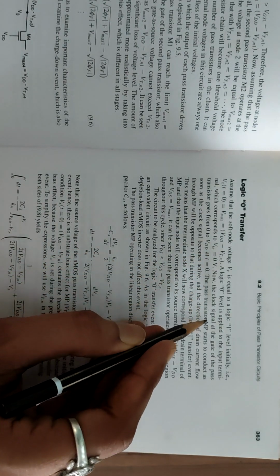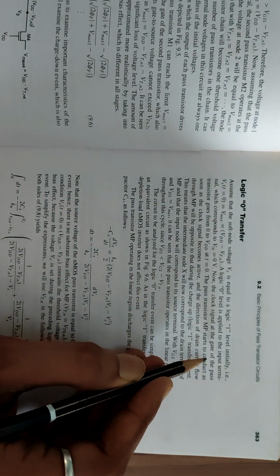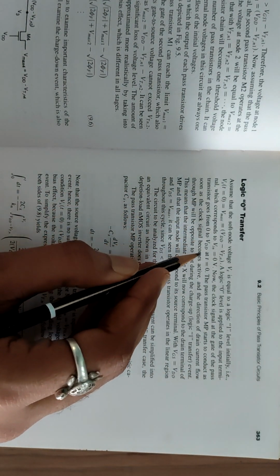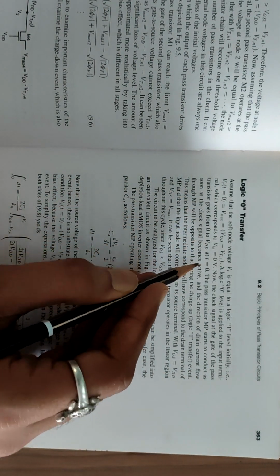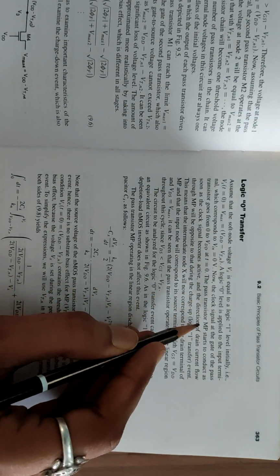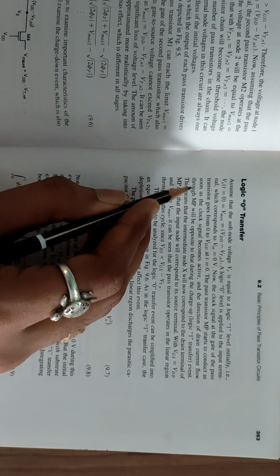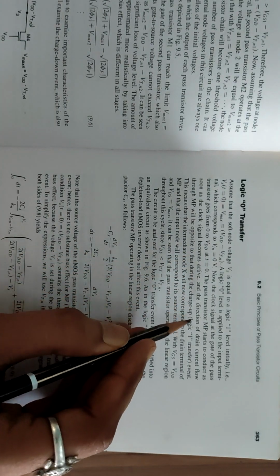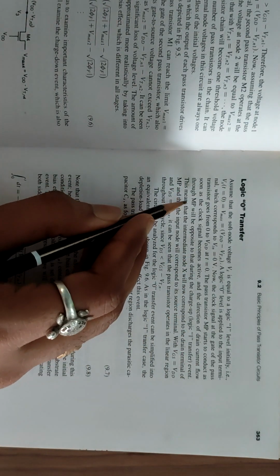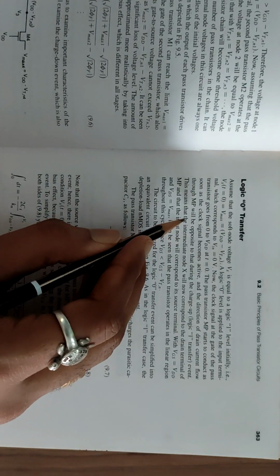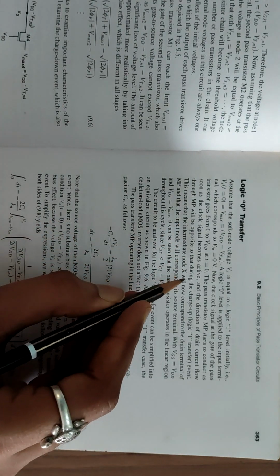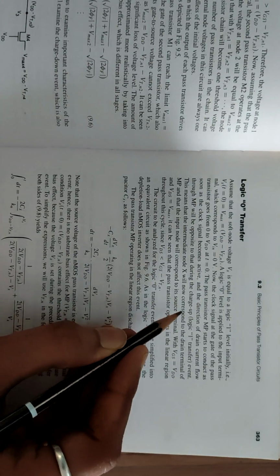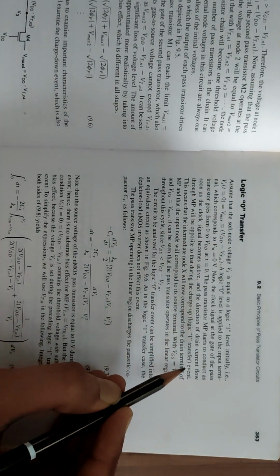Now the clock signal at the gate of the pass transistor goes from 0 to VDD at t equal to 0. The pass transistor MP starts to conduct as soon as the clock signal becomes active, and the direction of the drain current flow through MP will be opposite to that during the charge up logic 1 transfer event.